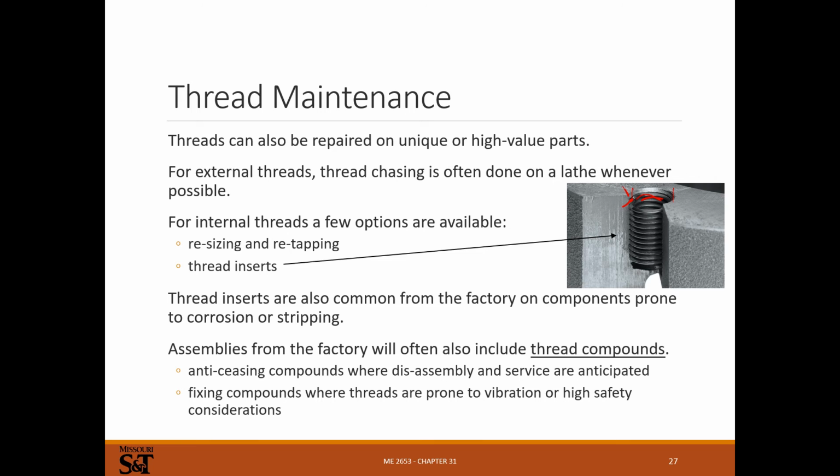And for aluminum, the Helicoil is going to end up being stronger than the original aluminum was, so it ends up being better than it started if you do it right. So as long as you've got room to drill a bigger hole and get a Helicoil in there, it solves the problem. Helicoil is a trade name. There's other methods of doing this too. I've used a few of these, whenever you pop threads out of something expensive, like usually an engine or something like that. It's an option for fixing.